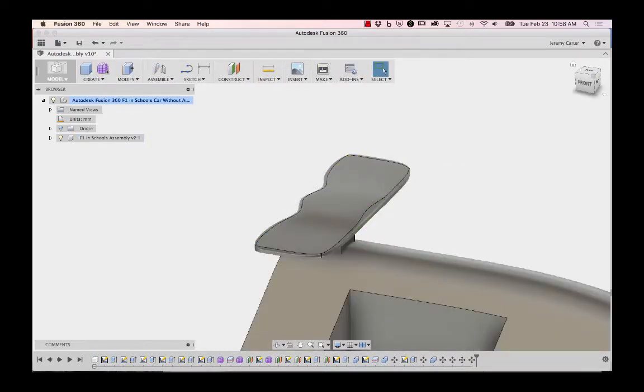Note, if you've received an error message, you have pushed the edges too much and they have crossed over. Look at the T-spline lines whenever you edit the sculpt environment. They cannot cross over. Save your work. You will now edit the body of the car.